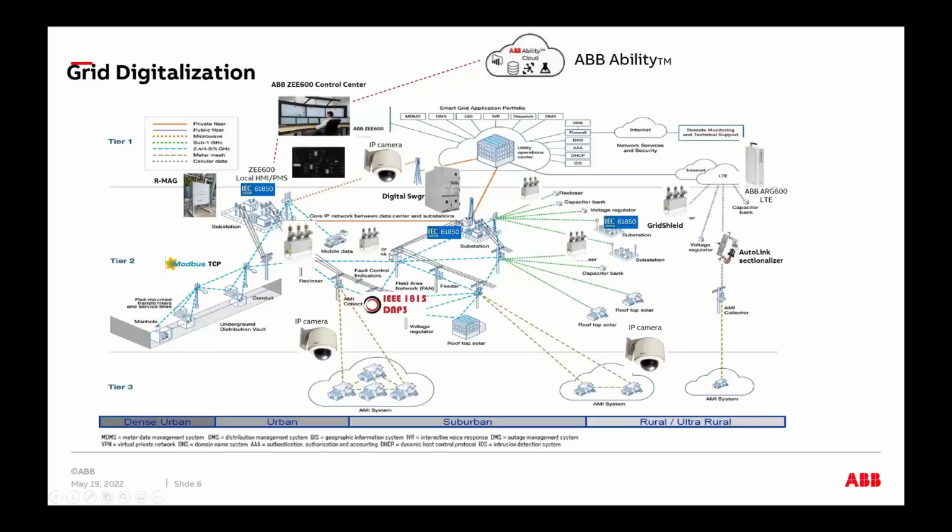So once you do that, you have all this grid that I'm showing you here. All those devices have been upgraded. They meet the spec of digitalization of the network. Now, what do I do? How do I pull all this data from the substation outside the fence? You look at it as a whole puzzle, right? You're pulling this data to bring it to an NCC room or SCADA or control room, and that data will turn into information.